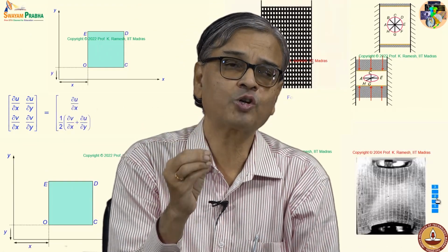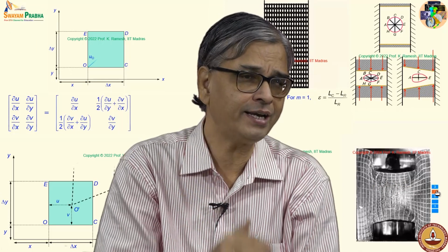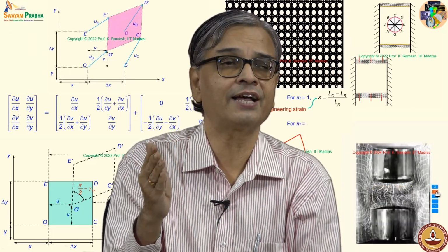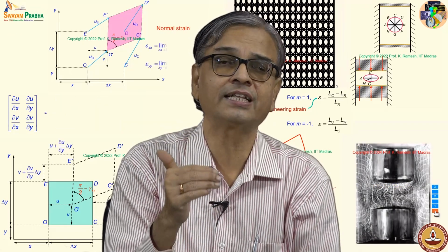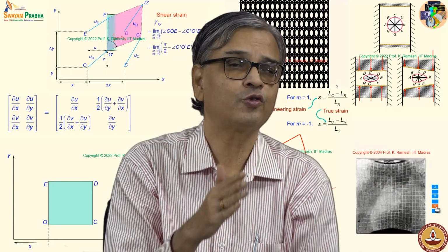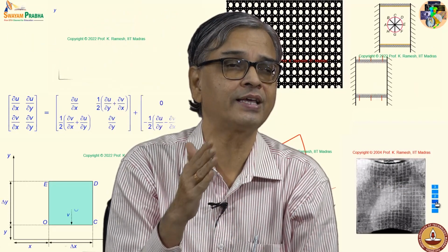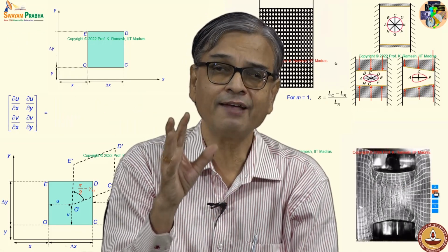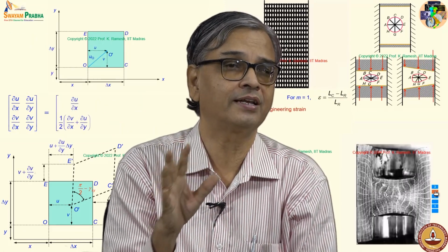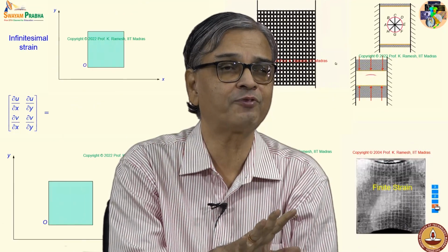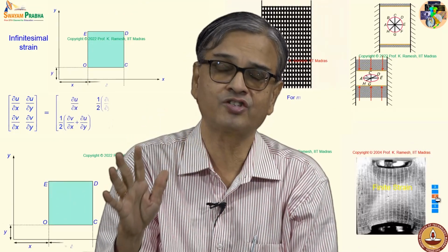Then we developed concept of state of stress at a point. Similarly, we have looked at from that graph started with change in length by original length as strain, and we have said if you have epsilon x, epsilon xy and epsilon y, it behaves like a tensorial nature, and whatever the concepts that we developed for stress you can find in strain.